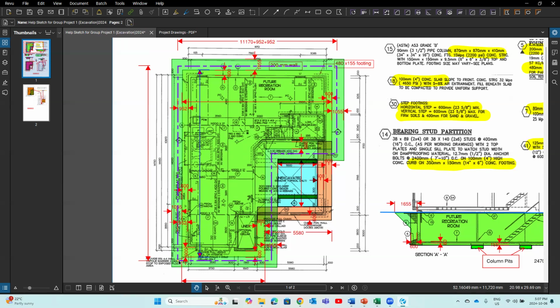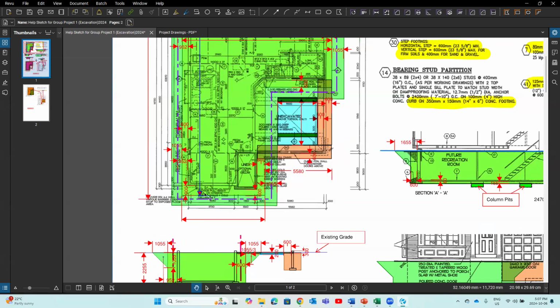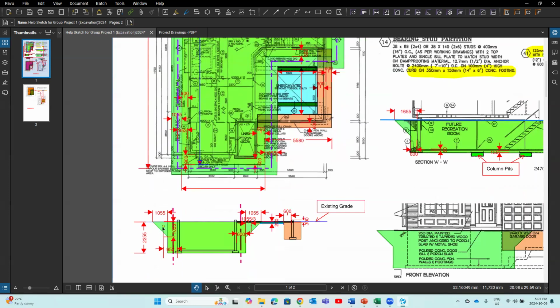The perimeter is a length, okay? It's a length, 2D. You need to think in this way: you stand there, it goes all the way around, right? That's a travel distance. You go back to the same point. After you get the length, you multiply by the cross section of this triangle, you get the volume. You add them together, you get the total volume of basement excavation, right?